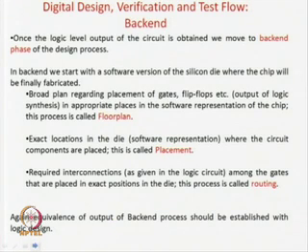In the back end, as I already told you, you actually make an idea of where you will place the gates, which is called the floor plan. That is the overall plan: here I will put the AND gates, here I will put the adders, here I will put the multiplexers, here I will put the memory block and so forth. That is called the broad level placement of your gates in the die. That is called the floor plan.